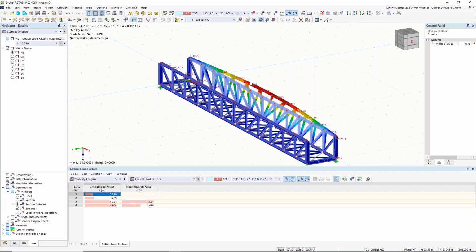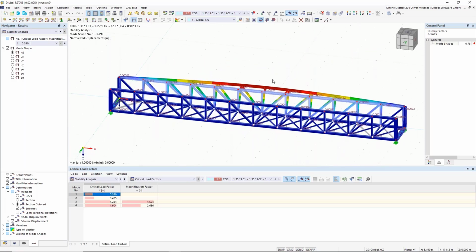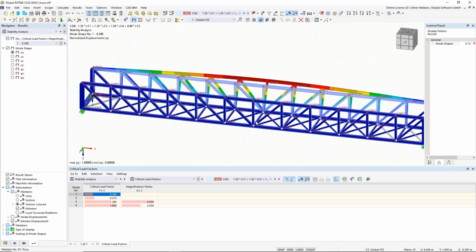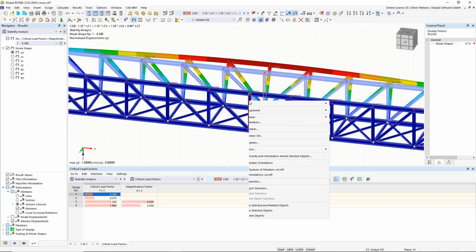That would not be sufficient, but we can now think of ways how we can enlarge the load factor and also the buckling resistance of this member. What would definitely be good in this case would be to create another frame, just like the end frame, here in the middle of the structure. In my example, I want to create in this middle another frame that can hold this top chord here. For that, I want to choose the member type of those two vertical members.